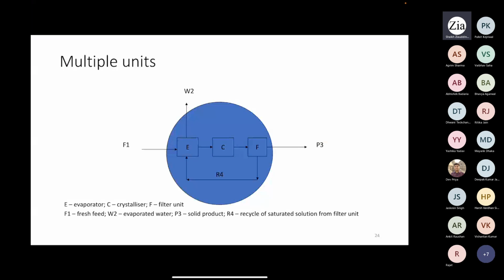Now, after bringing that to the industry premises, you will do the real upstream work, that is purification. Like with wheat straw or rice straw, now you need to have some sort of separation. That separation could be based on the size, and you may need to go for washing. You will wash with different kinds of washers.